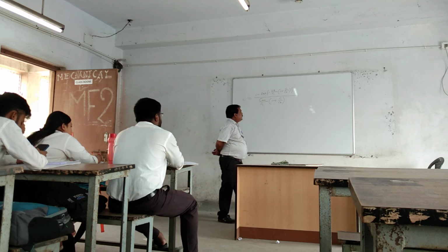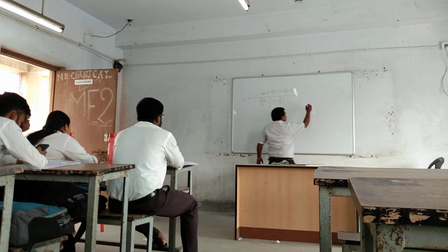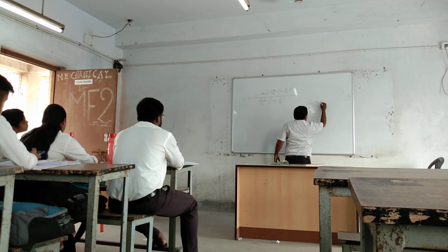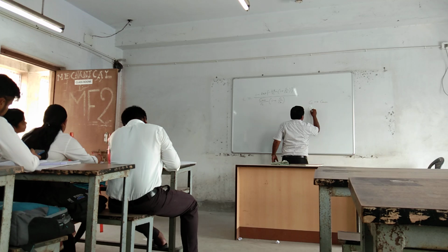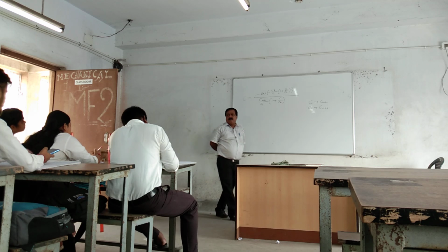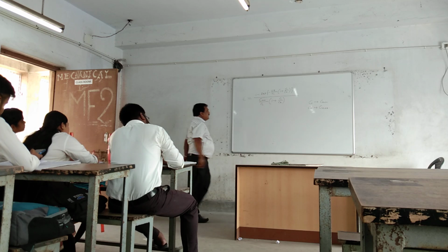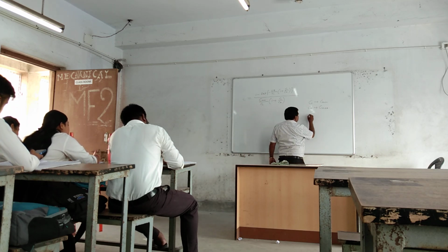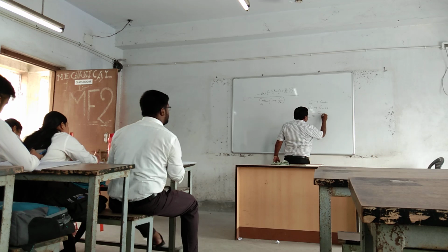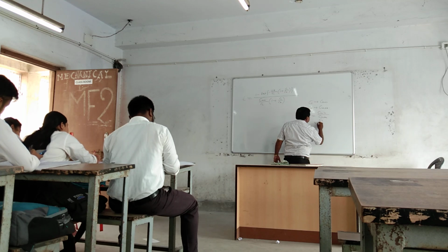Okay? Now see, of the two fluids, one is cold and another is hot. So one should be minimum and another should be maximum. If we consider CC is minimum and CH is maximum, then by definition C is equal to C minimum by C max, which is nothing but CC by CH.